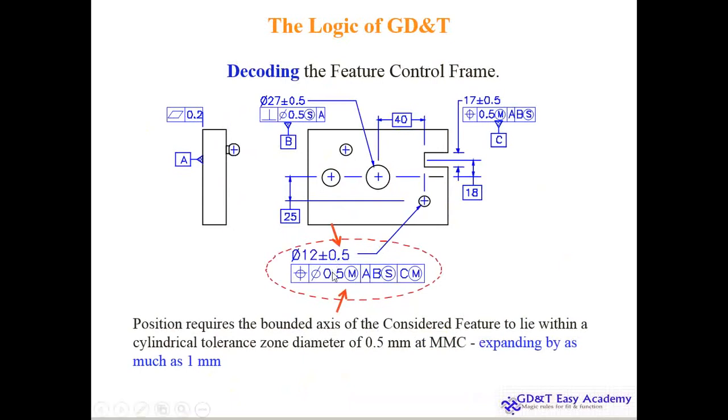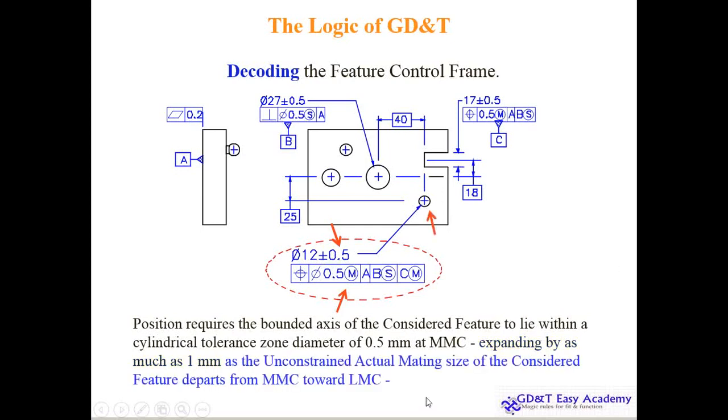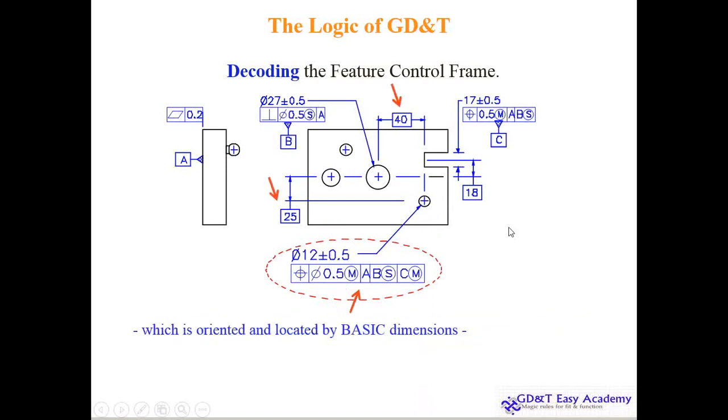This 0.5 and this 0.5 will be added, and it can expand. Expand is not with respect to axis. This diameter can also deviate, and axis can deviate, and collectively it can deviate 1. And you can see the departure of this particular condition because of the collective effect of the dimension tolerance and geometric tolerance for controlling the orientation, position, size, form control is now addressed.